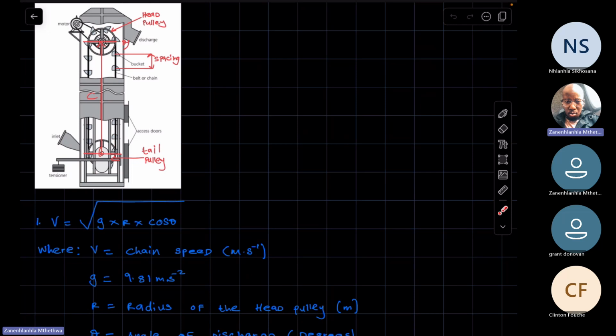So essentially, it's two times the center distance, because you are accounting for the length of the chain this side and this side. So the length will essentially be two times the center distance, accounting for this side as well as this side, from this center to that center. But because you're considering both sides, you say two times the center, plus, and then you account for the bit of the chain that goes around the two pulleys.